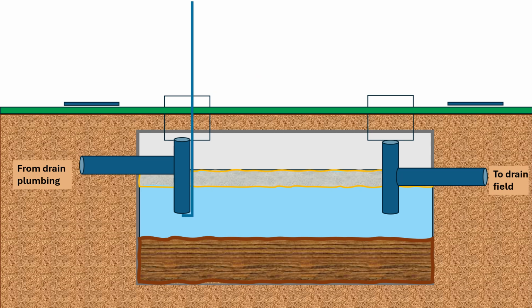The last measurement you'll make with the scum stick is to find the bottom of that riser, or in other words, the outlet or inlet of the piping. So you'll lower your scum stick down and pull it gently up against that riser, and then make a third mark. And this will help you to get the distance between the scum layer and the inlet or outlet piping. And that's that degree of safety we had talked about, that you want to be at least 3 inches or more.